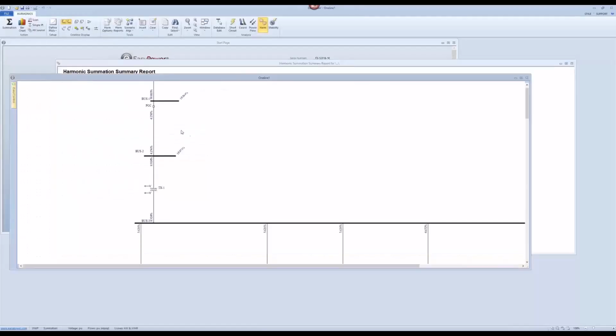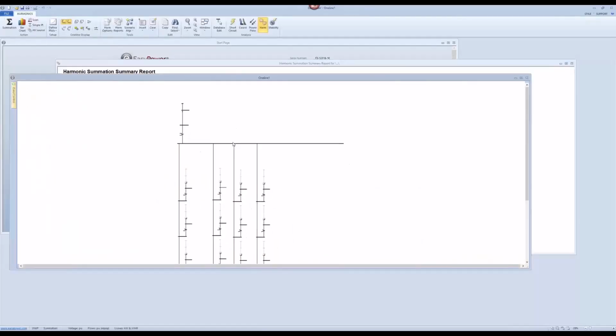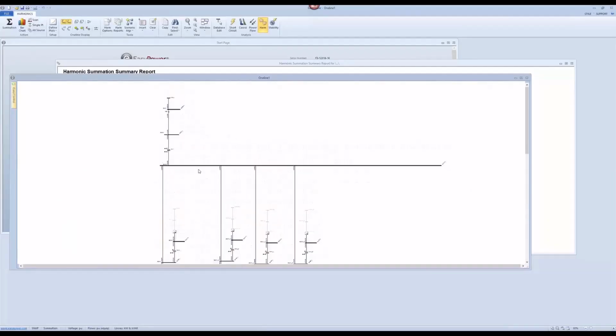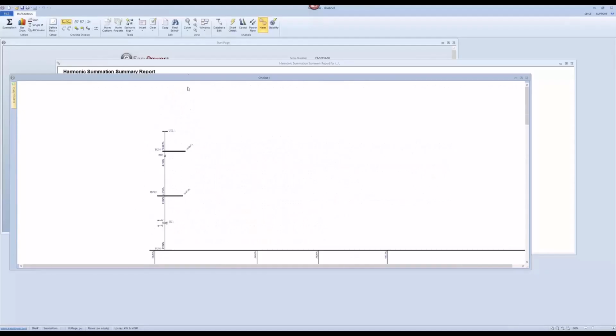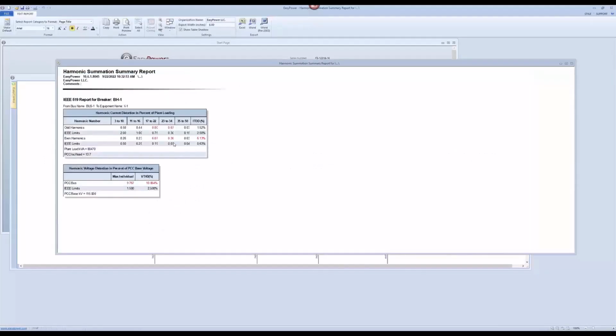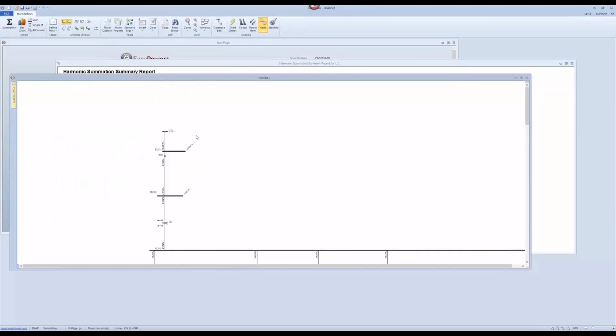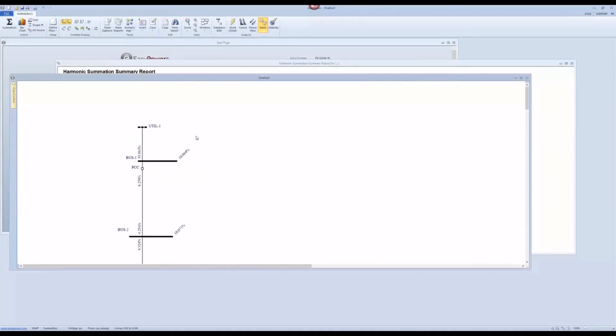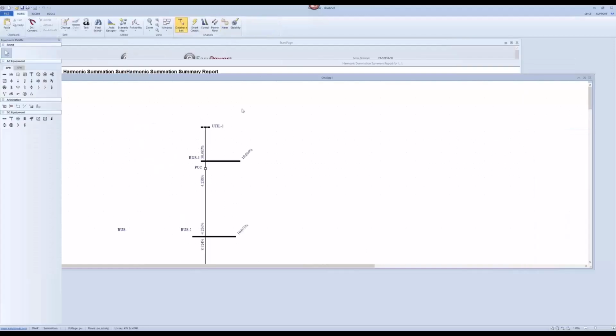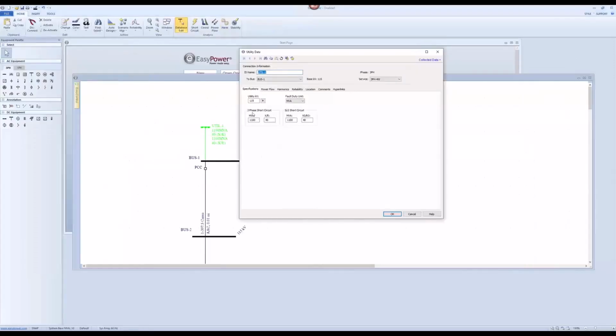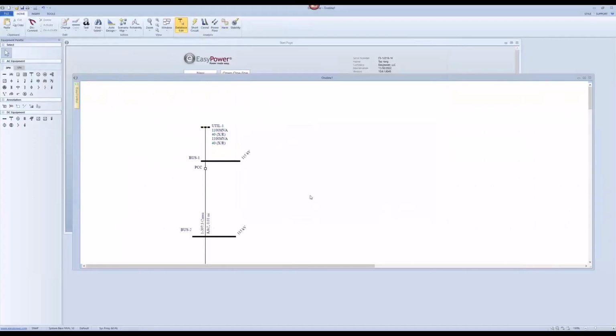captures the whole process of modeling an IBR-based power plant in EasyPower and evaluating the harmonic performance for the project. We intentionally created some issues there because there are some issues we have to fix. And the very simple fix, again, it's not a real fix, but fictitious for the purpose of discussion only, is to increase your short circuit ratio of the utility, right? In a stronger system, you should have less problems like that.